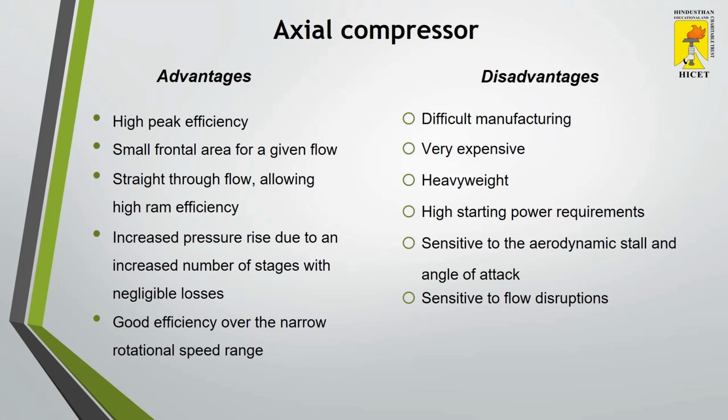The disadvantages are that it is very complex to design first of all, then it is difficult in manufacturing, and expensive because it is difficult. It is heavier in weight when it comes to multiple stages, starting power requirements are high, and it is sensitive to aerodynamic stall and angle of attack, and sensitive to flow disruptions.